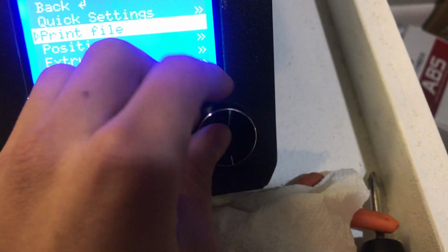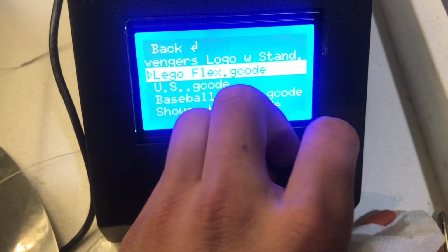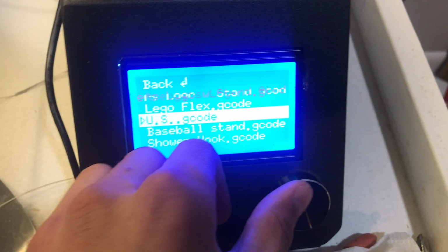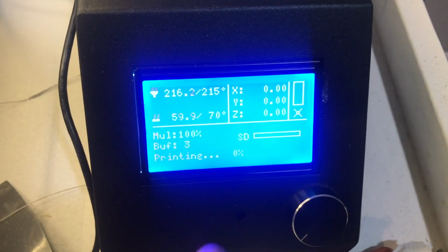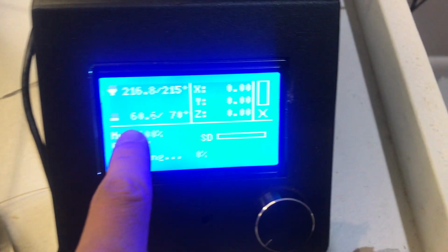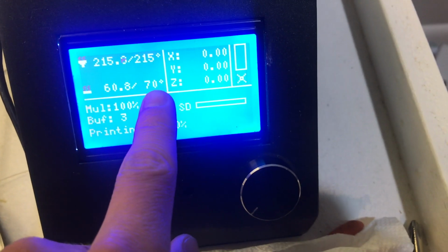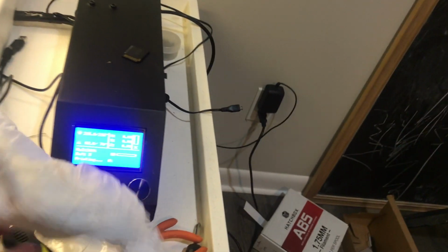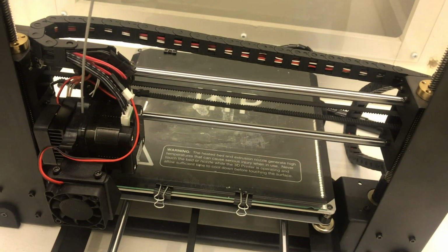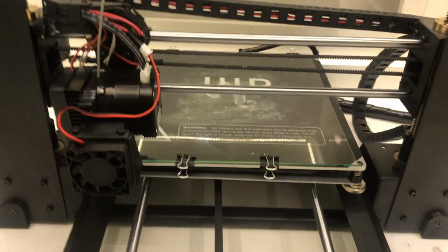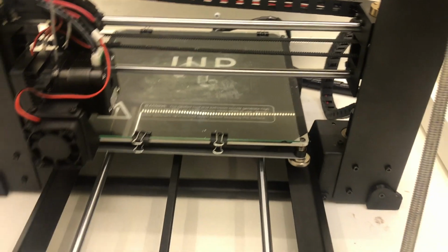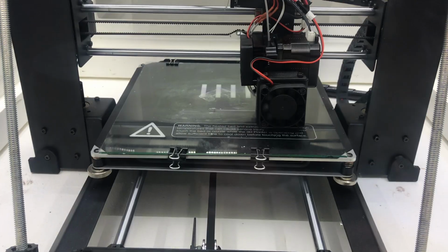will automatically change it. Once you're ready to print, press the file that you want. And that will change. This will keep climbing until it reaches 70 degrees Celsius. Same with this. A recommended tip, keep a damp paper towel by you and some glue sticks. To get a good first layer, lay down a layer of glue on the print bed itself. If it dries, use a wet paper towel and wipe it off.